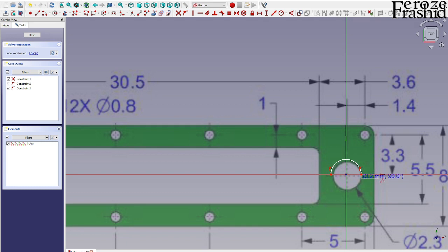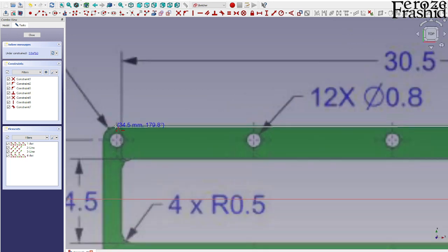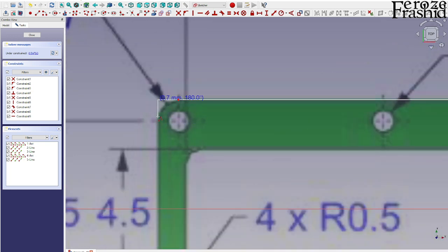Okay, I'll have to be careful with the polyline, because it has its own suggestions from one point to another, and you can change the suggestion by pressing M every now and then. Like here, now I got this line, but I'll have to come back and make that tangential anyway.